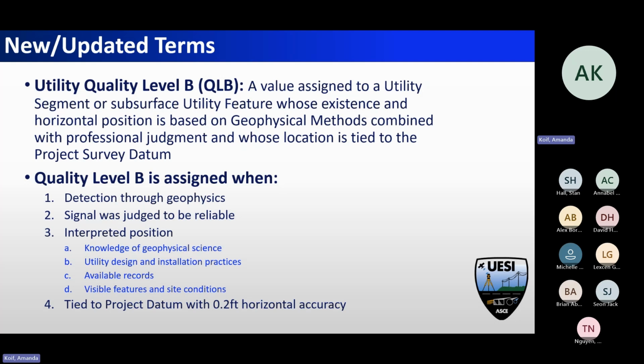Is it all tied to the project datum? If it's not in the right spot, the data is no good if you shift it another foot or two off, or use grid instead of surface, and the project's in surface. So make sure that you're in the correct datum and that you're tied to that datum with a 0.2 horizontal accuracy.